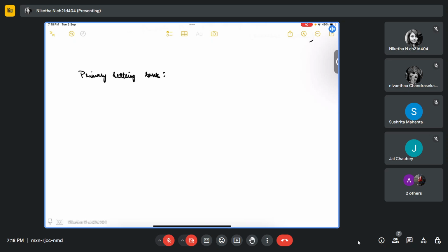Okay, so the grit chamber will remove all the inorganic particles that are heavier than the organic solids. In the primary settling tank, we'll remove organics which are slightly heavier and which can settle down. Here we will provide a longer retention time when compared to a grit chamber. So here we can remove settleable solids, and even the floating substances can be removed.